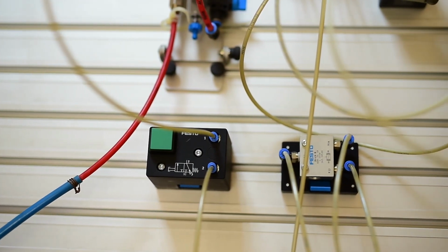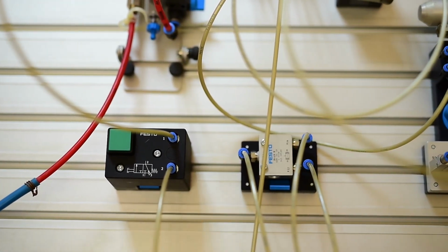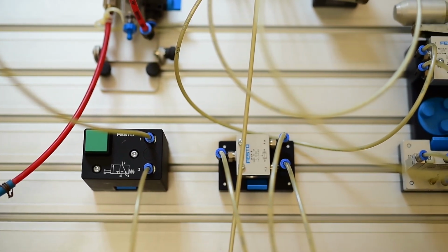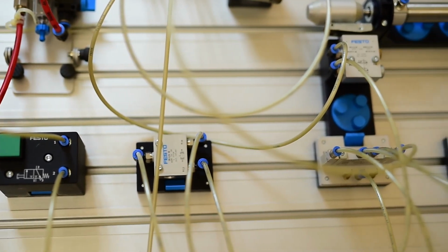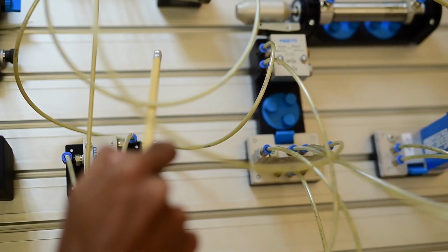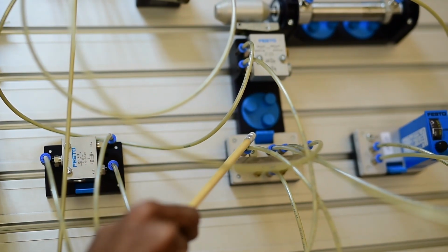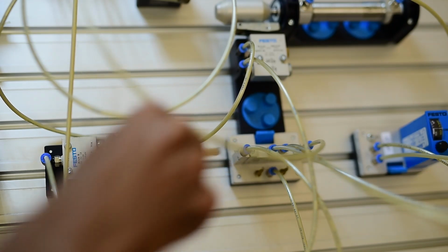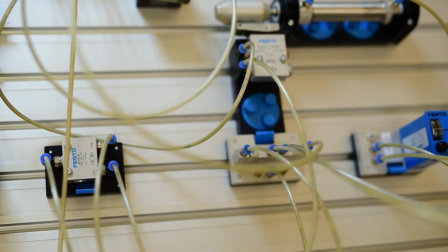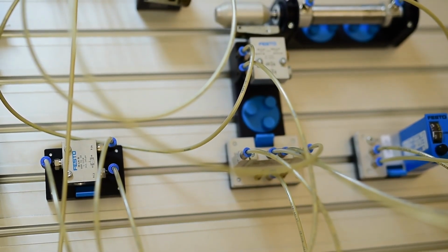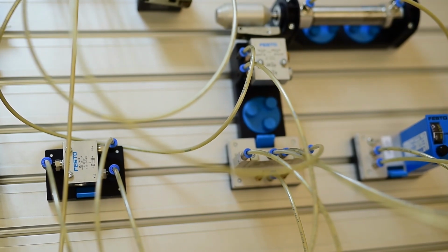This is a two pressure valve, which, having air supply on either side, allows a passage for the air to flow through the opposite side and the common point. This 5/2 way impulse valve is also controlled by two air supplies. Depending on which supply is present, its state changes back and forth, allowing air to flow through certain paths.